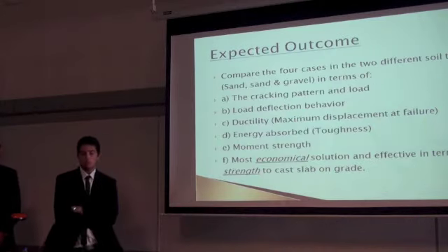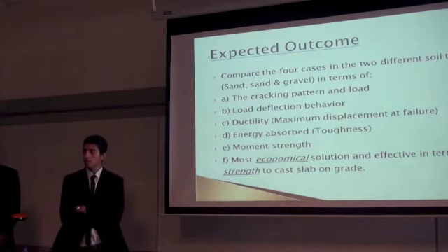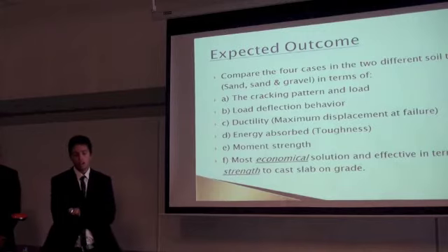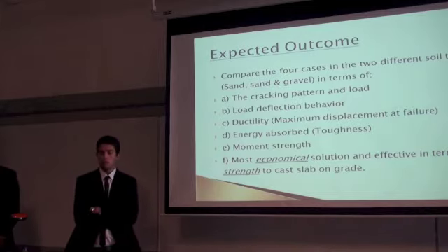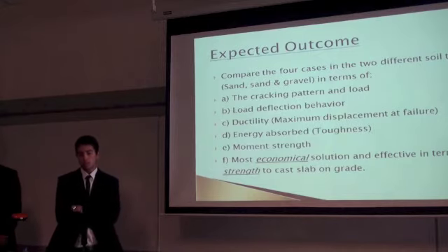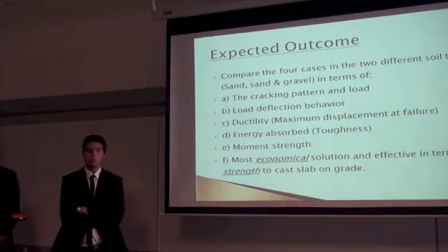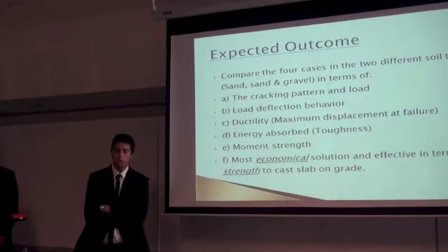The expected outcomes are to compare the 4 cases in the 2 different types of soil rested on: the cracking pattern and load, the load deflection, ductility, energy absorbed, moment strength, and most important, the most economical and effective solution in terms of strength to cast slab on grade.